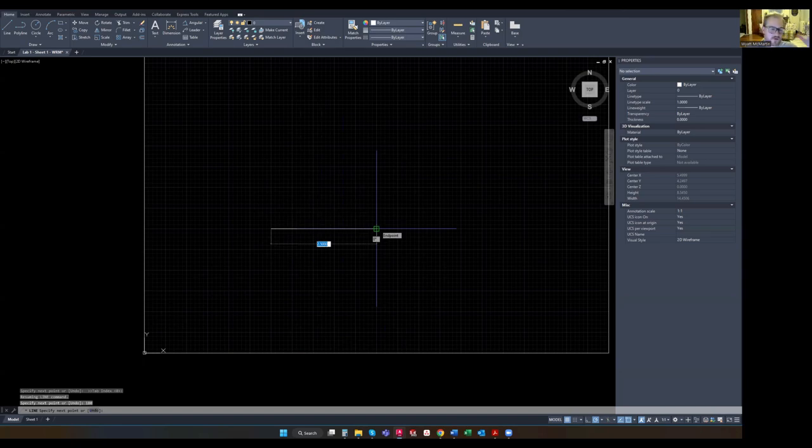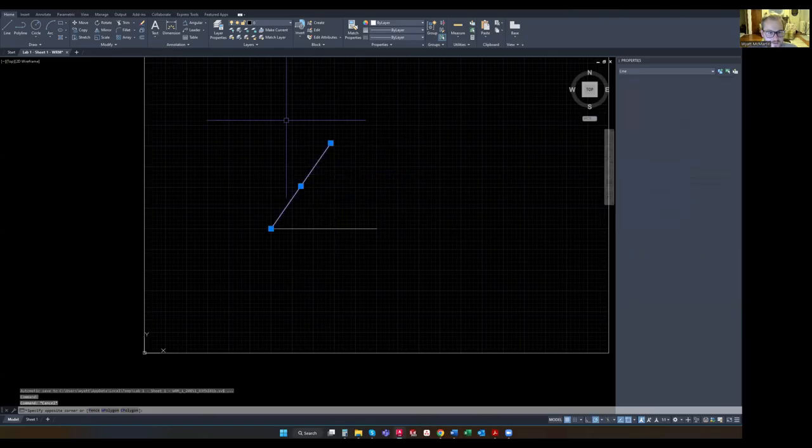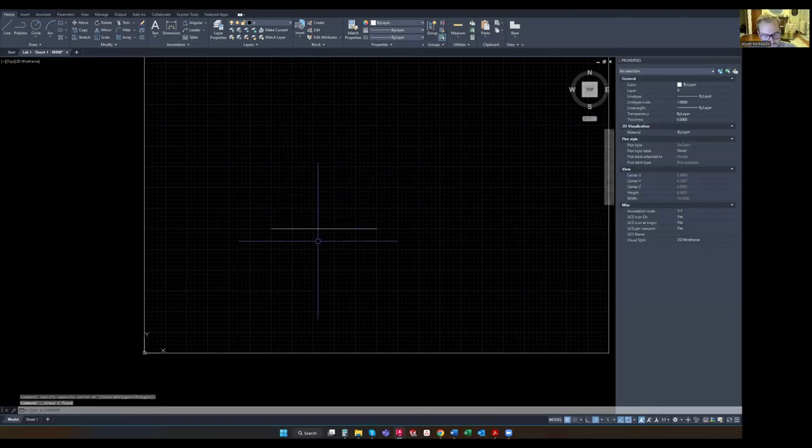And that's kind of how AutoCAD keeps track of things. You can see also, it's keeping track of the distance of my line and the angle of my line. So right now, the distance in the little box there is highlighted in blue, so it's asking me for the distance. Then when I click tab, so if I say 2.5, enter, oops. Let me grab my line again here.